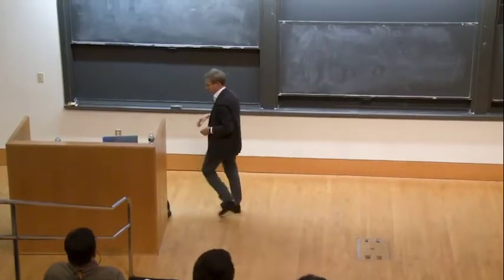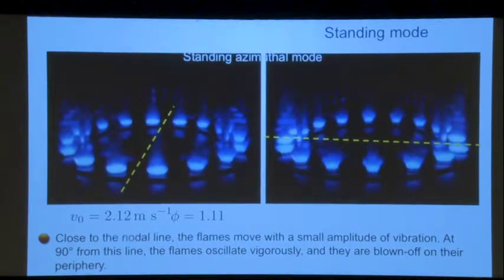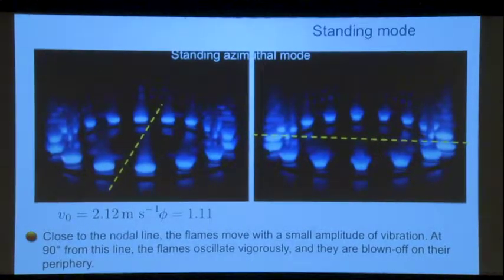In fact, what we found in this combustor with these injectors is that you could have a standing mode, you could have the spinning mode, they would be steady. And in this case, much was driven by the plenum, what was happening in the plenum. In the other case, it was more the chamber, but in this case, it's the plenum.